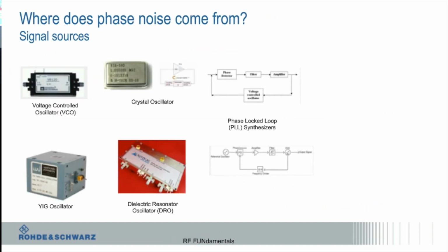Okay, so some typical devices. There's a VCO, or crystal oscillator. Obviously, a crystal oscillator is intended to be something fairly stable, and there's varying degrees of how stable one can make it. There's ones that have things to control temperature effects, to help dampen vibration effects, things like that. So that's kind of a more stable reference oscillator.